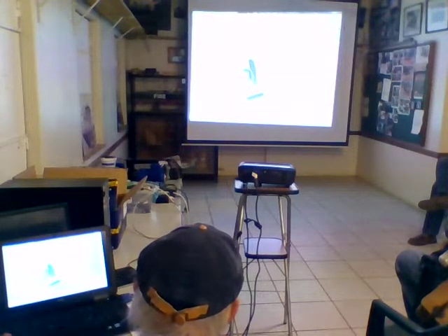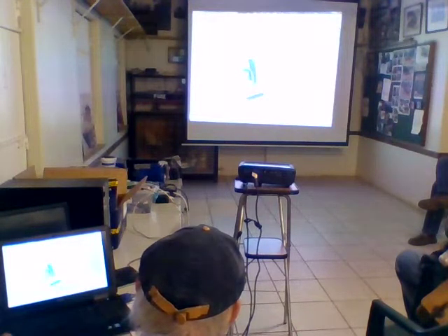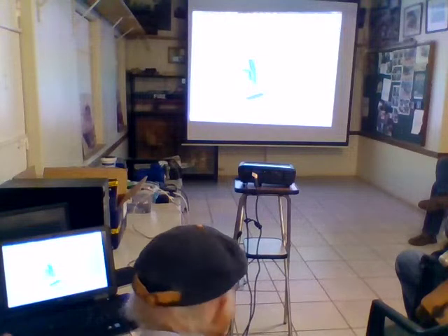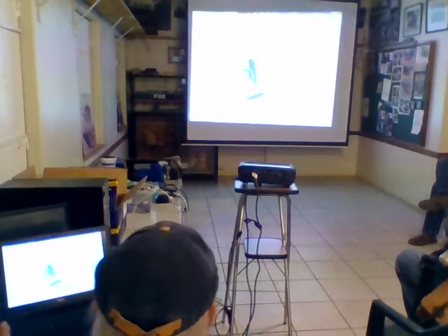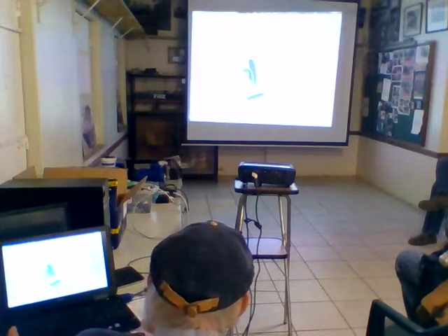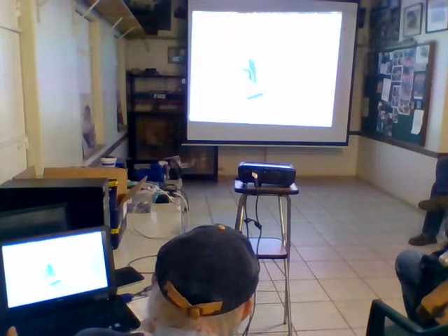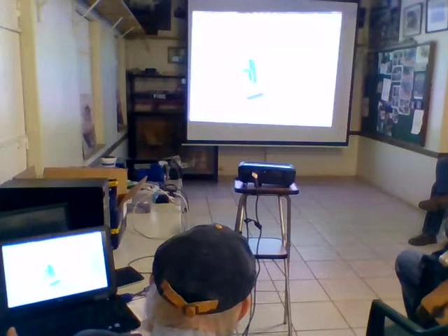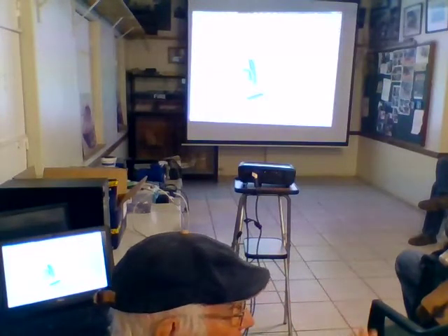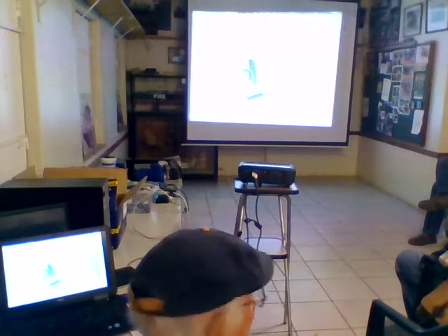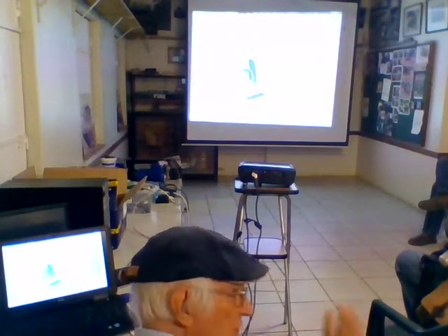I found that this part, and I'll show you what I mean, I think I'm going to improve in the next version. I'm going to fill that angle up a little bit, make it a bit stiffer there. There's a bit of rotation, bending here in this area, but putting these extra blocks in here helped tremendously to keep the verticality of the vertical axis, so that it doesn't tilt when you push forward and backward.